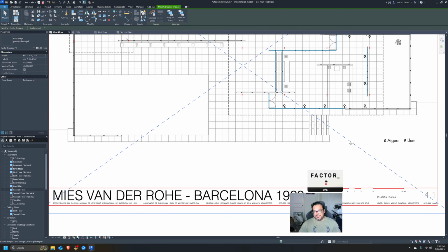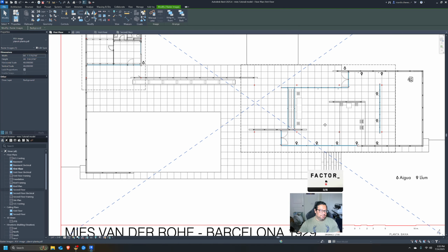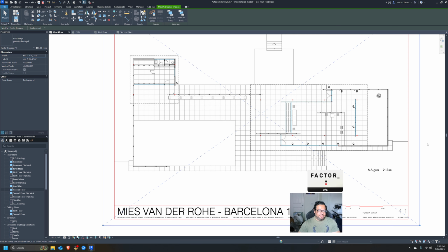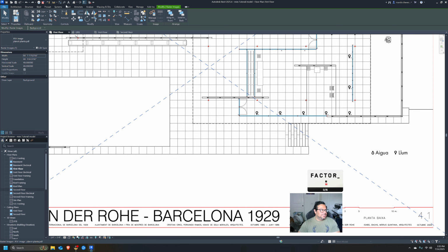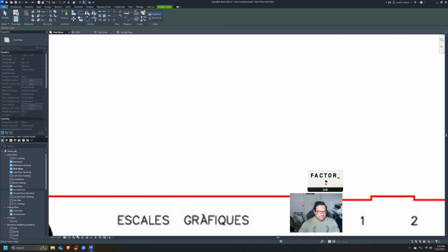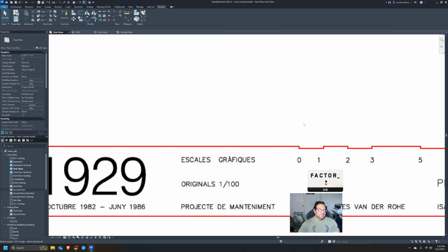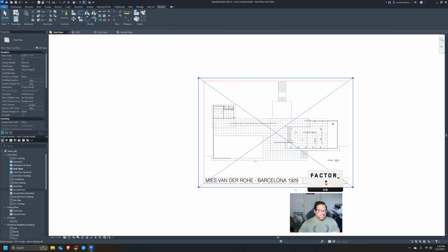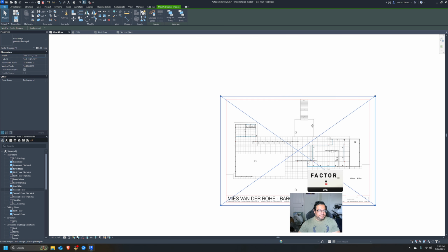Anyways, so yeah, that's how we scale the drawings, right? If we want to scale either way, you're not just limited to the X direction, you can scale in the Y direction as well. So for this, let's click on scale, click here, and then we do 3 feet. And we're done. Now we're going to move it a little bit to the center.